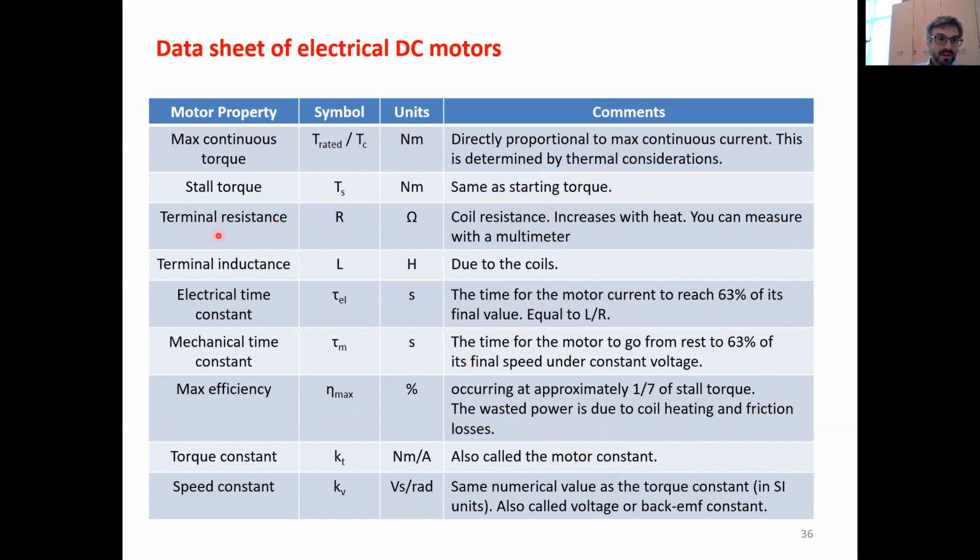The terminal resistance, the resistance of the coil, measured in ohm, and you can measure it with a multimeter usually. The terminal inductance, measured in Henry, the inductance of the coil. You can have an LCR multimeter, I think, to measure also capacitance, to measure that.